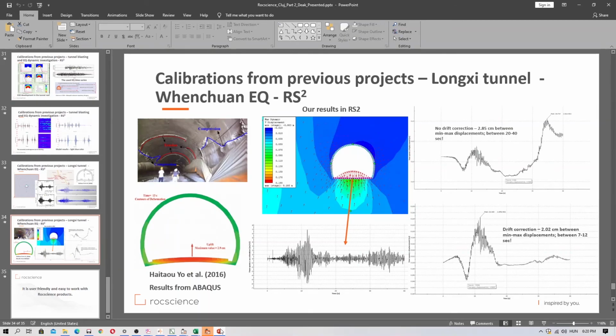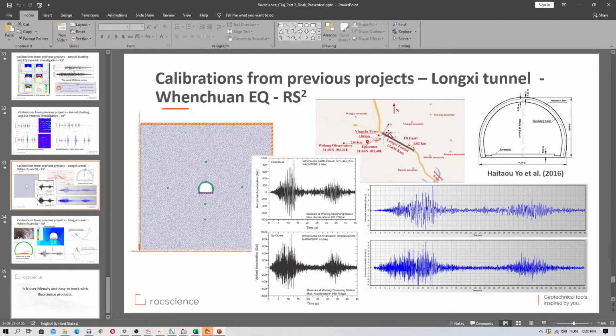It makes an angle of 33 degrees with the horizontal east-west direction, and 57 degrees with the north-south direction. So the horizontal X and Z input motions are obtained by orthogonal decomposition of the recorded east-west and north-south accelerations. Our simplification is that we excluded this fact. So mainly in our modeling we use the east-west direction and the up-down direction.